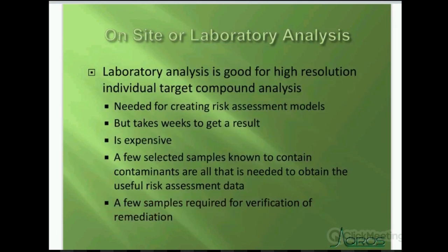However, I'm not trying to knock lab analysis, far from it. We all need it, but we need good quality lab analysis. Good quality lab analysis is brilliant for your high resolution individual target compound analysis. You're using good quality GC-MS, and you need this for creating risk assessment models. But because it takes weeks to get a result, it's really only suitable for site investigation. To do it properly, it's going to be expensive.